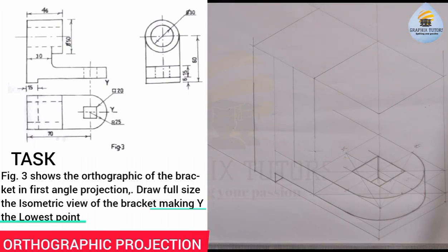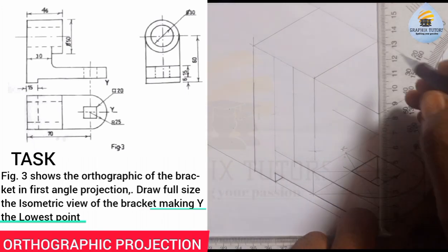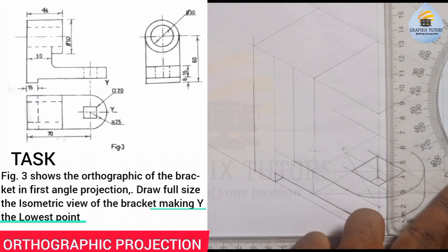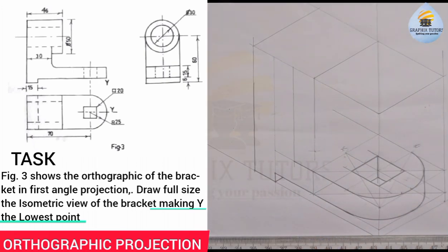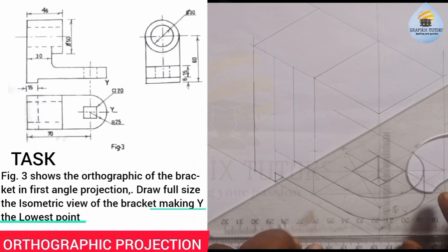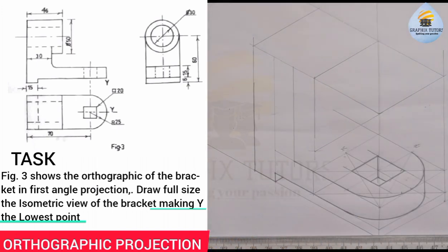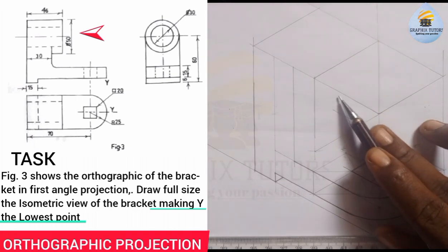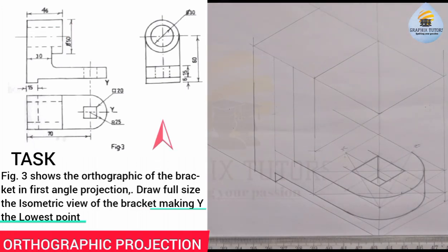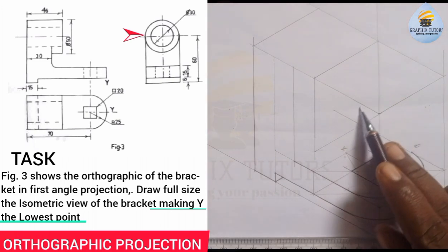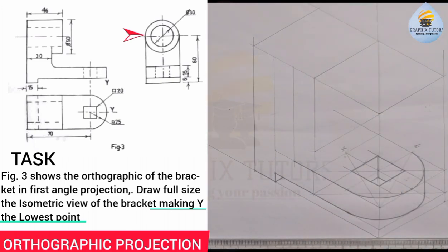So once I have done that, I'll bring this here. It's already coming down. And I'll just close it up to form my box because I want to draw a curve there. What do I mean, a curve? If you look from here now, we just have a rectangle. But looking in this direction, you'll be seeing the end elevation. So the end elevation is telling me that it is a circle. This circle you see, meaning that here it is a circle. Right?